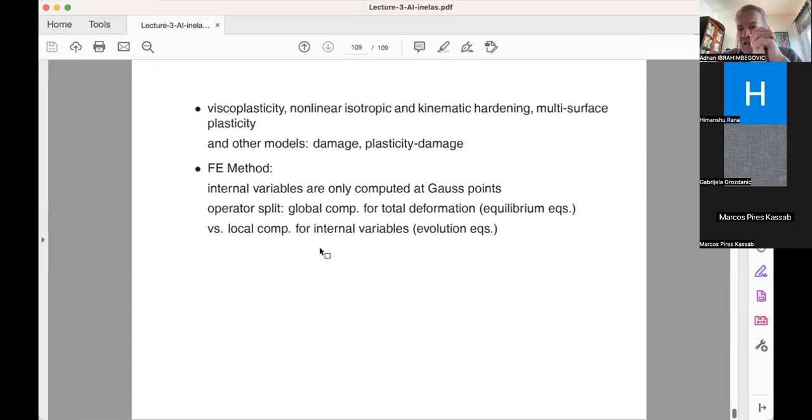Then I took plasticity and I showed you, next to this 1D case, that the 3D case for Mises is rather similar, other than using the bold-faced letters, because a single stress component is replaced by the stress tensor, a single strain component is replaced by the strain tensor, and so on and so forth. And the reason you have these strange coefficients like square root of 2/3 appearing, but other than that, I'm still describing the same physics.